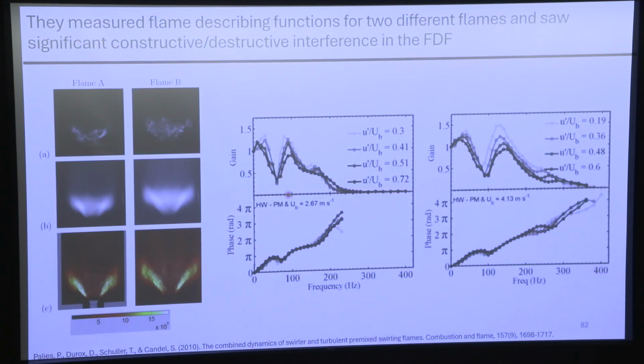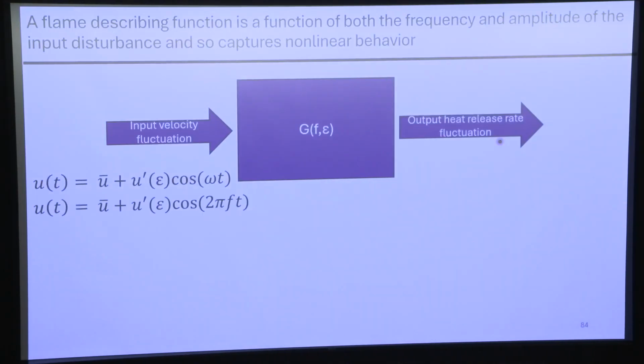We saw really clear nodes and antinodes in these transfer functions, right? This is beat-you-over-the-head obvious that there are constructive and destructive interference things happening. You must have multiple disturbances along this flame, and that's resulting in this pattern. And one of the things that separates this study from all the others, and why it has a gajillion references, is because they hunted that down.